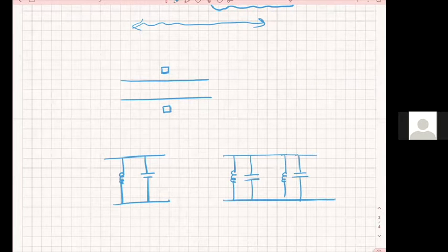What that helps me, I increase my inductance, I double it, and I make my capacitance half. Okay, it's all positive so far. That may not necessarily help me because a very small number twice is still a small number, and a very high number divided by 2 is still a high number, but I made it symmetric.